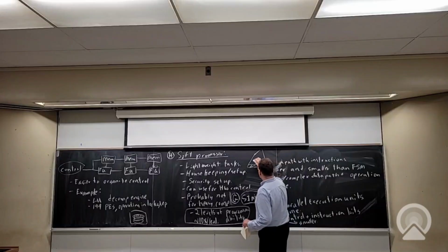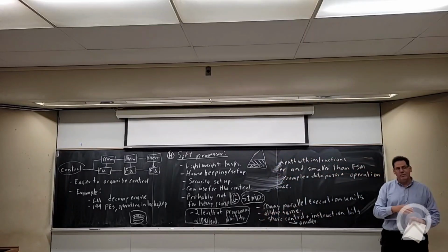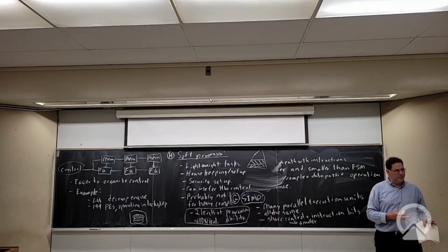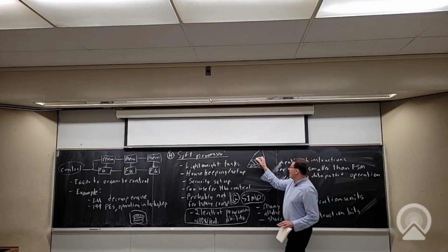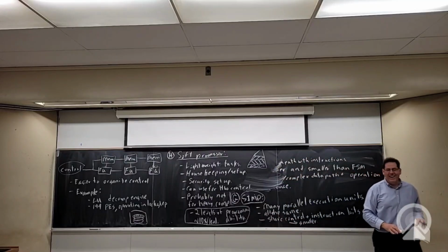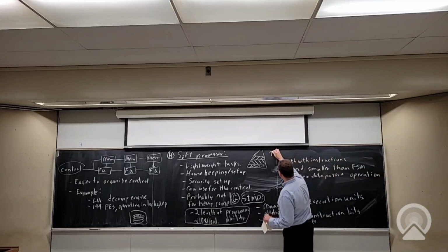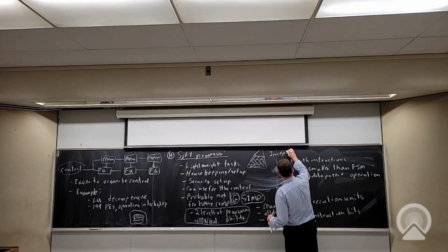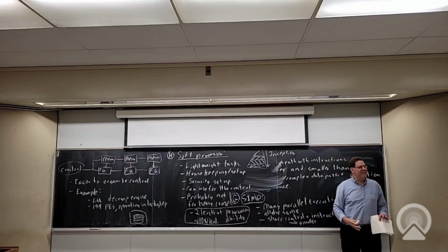On that FPGA, they built a virtual FPGA. They don't actually want to use the LUTs and wires in the FPGA. They use the LUTs and wires to make virtual LUTs and wires, which is now another factor of approximately 10x. And then on that, they ran the soft processor. So I was a reviewer of this paper, and I was very tempted to just basically call this Inception. If you've ever seen the movie Inception, with every layer they go down, things get 10 times slower, right? And that was effectively what their paper was.